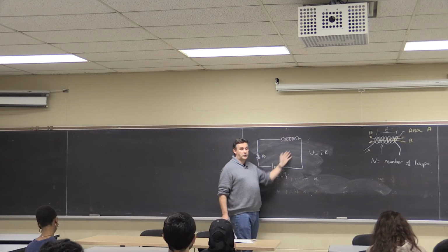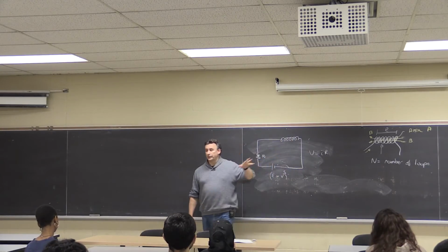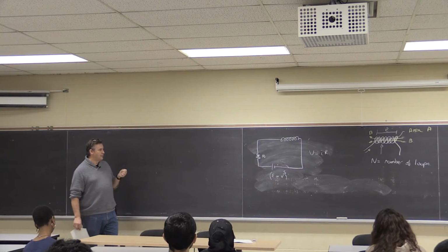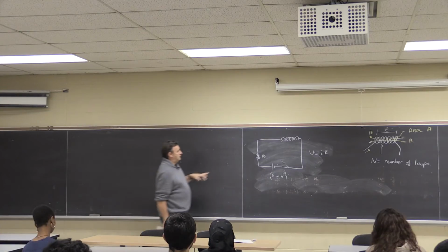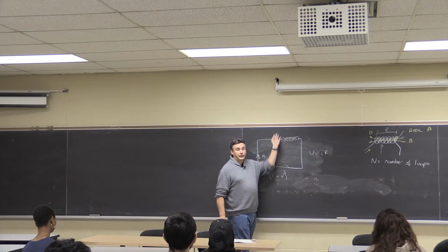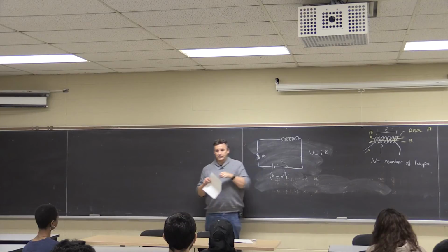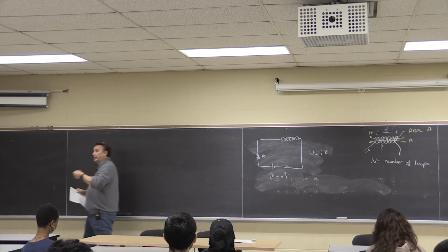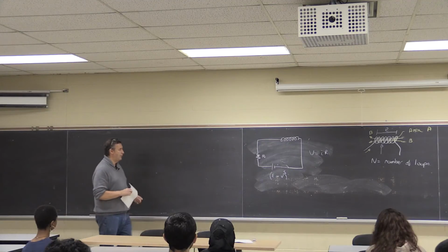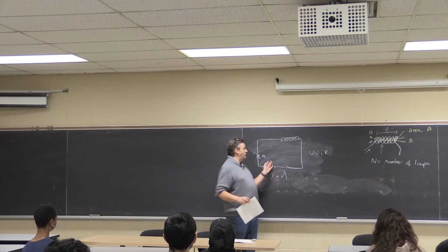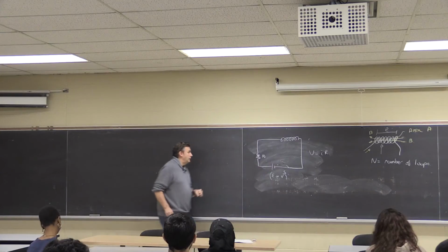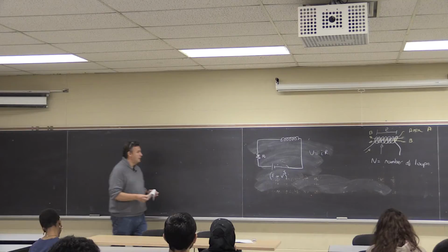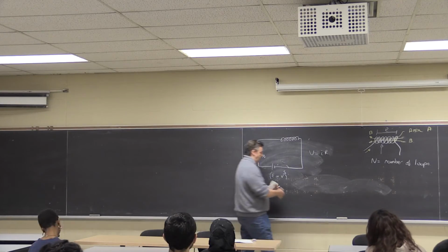Conversely, after this has been sitting here for an hour, and I open the switch, or I take the driving potential away, the current really wants to keep on flowing in the inductor. Because if it stops, it gets a changing flux in the opposite sense, and that's going to still try and continue and drive the current. Now, this is maybe not a good example because I break the whole circuit, but we'll analyze some variations on a theme later. So this is what we call self-inductance.